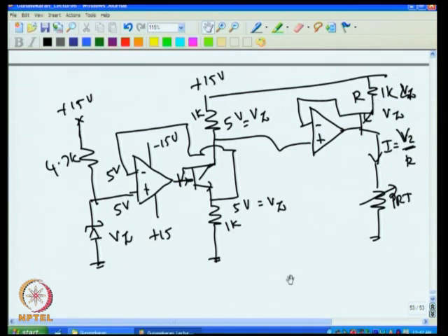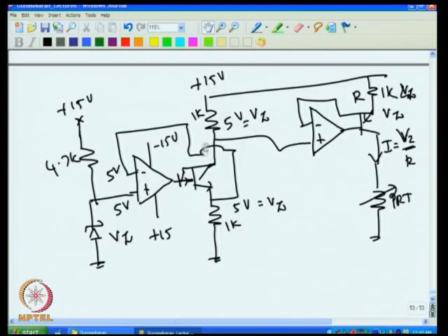So one has to be very careful when dealing with this, because we want to save one Zener which may have low temperature coefficient, but then we end up having resistance which is now producing much larger error than what we had thought. So one has to look into this aspect also when you are deciding on the circuit and saving the money.